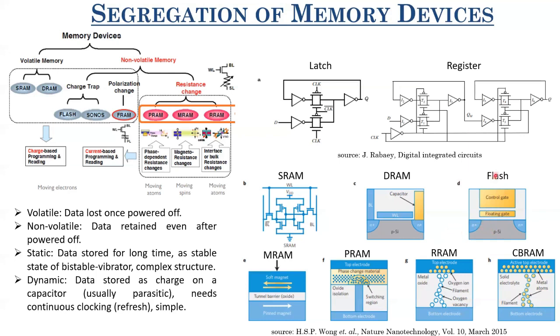Now what we have done is we applied a high voltage pulse on the control gate. Some amount of the channel charge has tunneled from this silicon channel through this tunneling oxide, which is SiO2, to this floating gate or silicon nitride layer. And now your silicon nitride layer or this floating gate has some charges. So if there are some charges in your gate oxide, the threshold voltage increases.